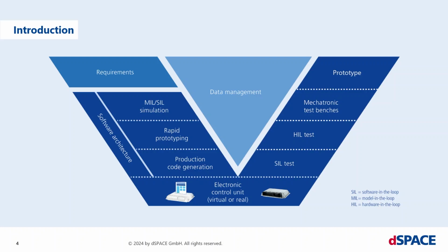If you want to have a higher test coverage, you can do hardware in the loop testing. That means we read out the output signals of your device under test, calculate in real time what would be the behavior of your environment, and feed back all the signals that normally your environment is feeding back to our device under test, but only on signal level.